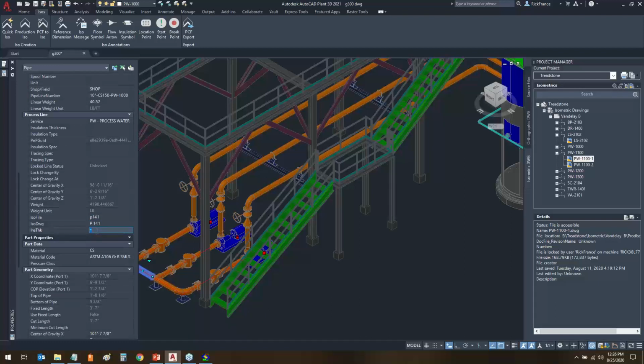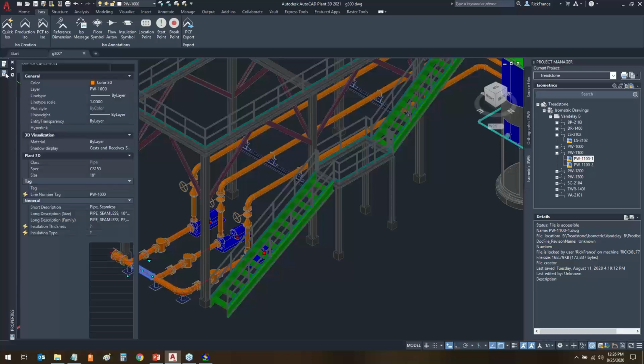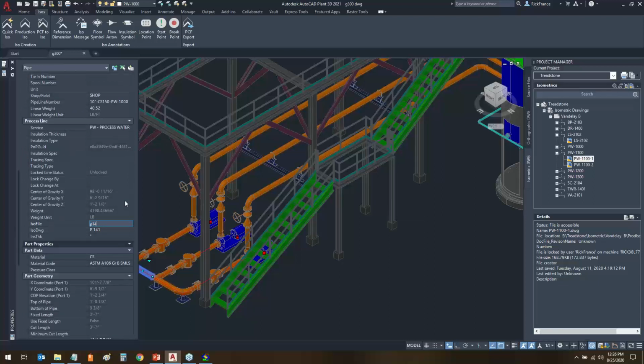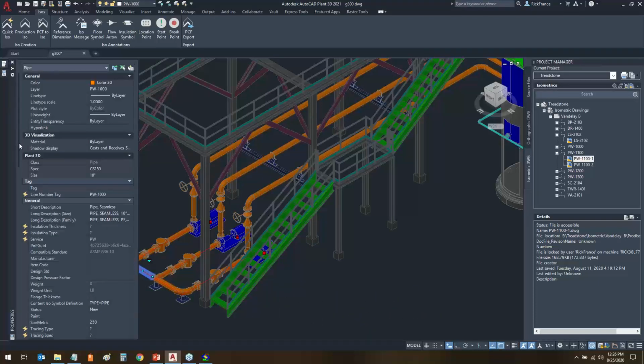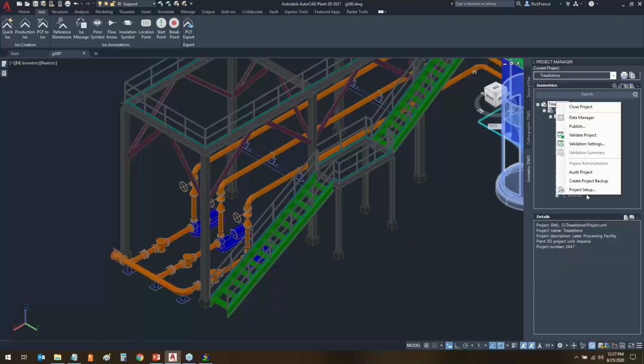There's no insulation thickness, so it's putting an inch sign in there, but the title block won't show it if that's all it has. But at this point it looks like information that could be changed. It acts like I could, and you can see if I try to change it to something else, it will take it. But as soon as I hit escape and come right back to the same piece of pipe, it's right back to the original hard-coded text. So you can't physically change it. So for that reason, since I've hard-coded this with those calculated properties, I don't want people to see them or to try to change them. So I'm going to change that in my project setup.